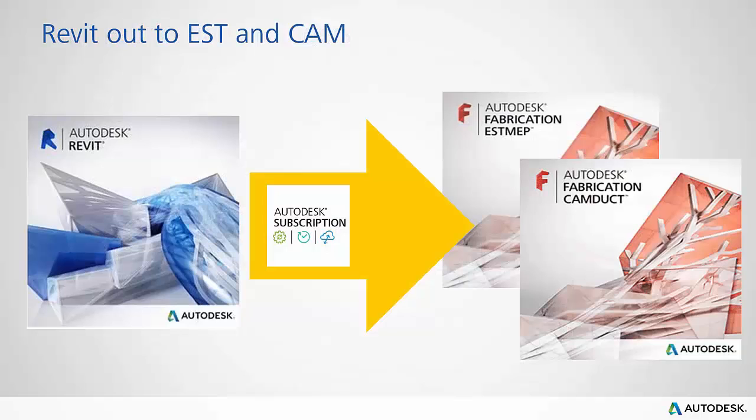Not everything is inside of the Revit MEP environment. There are still the fabrication workflows. So you can see when we go to do our estimation and work through CAMDuct for doing our nesting and then sheet cutouts and the laser cutters and plasma cutters, you send it out from Revit for that final stage in an AutoCAD environment.